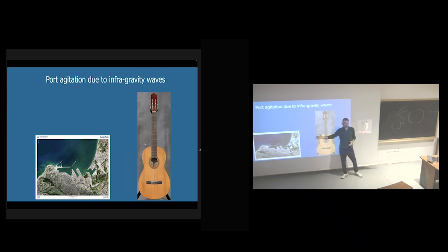It's the same with the harbor, just we try to plan it in the opposite way, so that it will dampen the waves. We don't want them to oscillate and resonate inside, and then you actually need to plan a harbor according to the infragravity wave regime that you have, and that's kind of a challenge, yeah? Because many times we don't have enough measurements, and we will talk about it, and we don't have a full understanding of all the generation mechanisms of these waves.